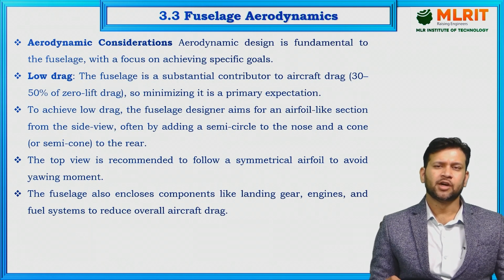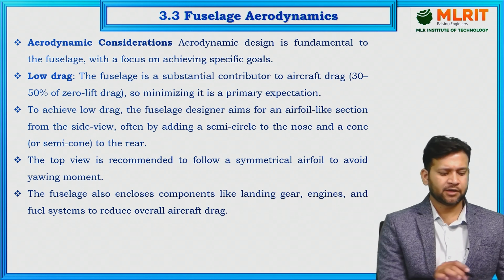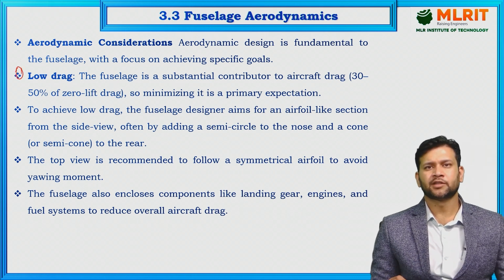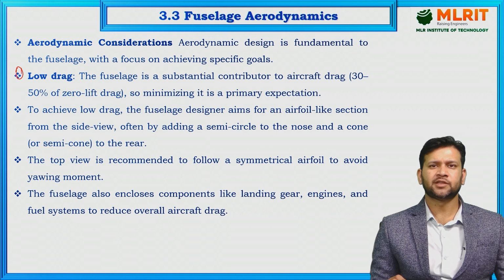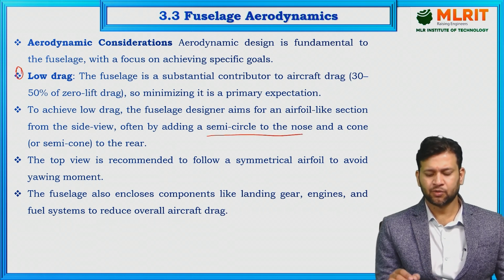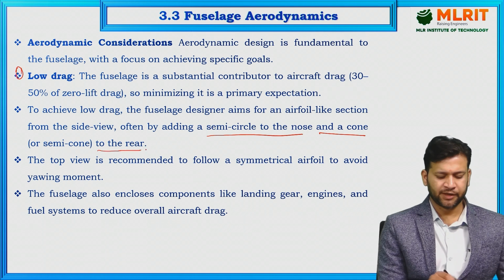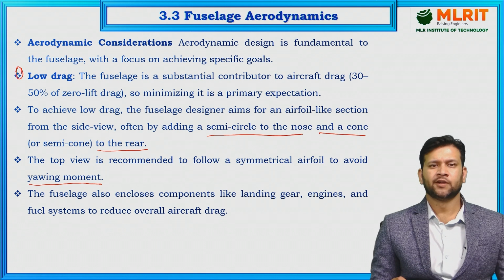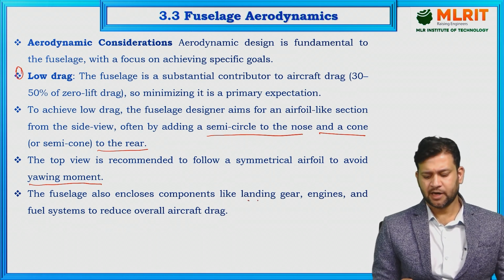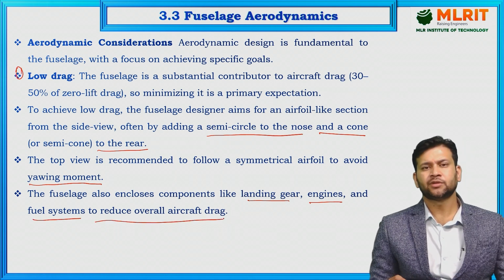Aerodynamic considerations. Aerodynamic design is fundamental to the fuselage with a focus on achieving specific goals like low drag. The fuselage is a substantial contributor to the aircraft drag, 30 to 50% of zero lift drag. So, minimizing it is a primary expectation. To achieve low drag, the fuselage designers aim for an airfoil-like section from the side view, often by adding a semicircle to the nose and a cone or a semicone to the rear. The top view is recommended to follow a symmetrical aerofoil to avoid yawing moment. The fuselage also encloses components like landing gear, engines, fuel systems to reduce overall aircraft drag.